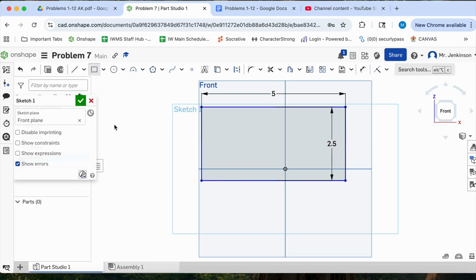Now we can start making our steps with the line tool, and I'm just going to click on the top line and bring this down. I'm not real concerned about the dimensions at this point. You could, if you wanted to, type in the dimension right there. It was 13/16. So you can actually just type in the fraction and then hit return, and it converts it right away to a decimal. And then I'll sketch the depth of the tread,